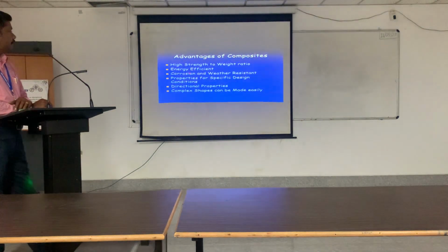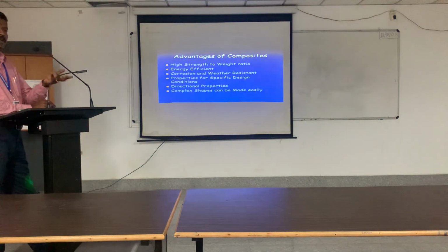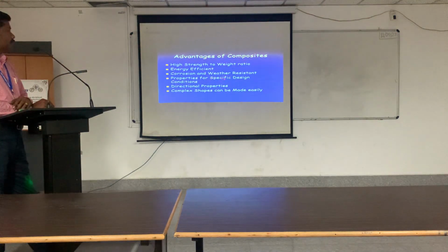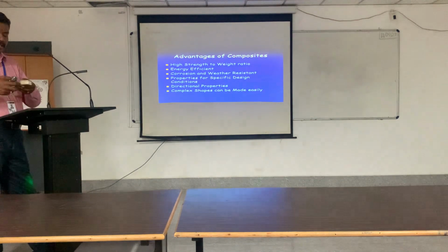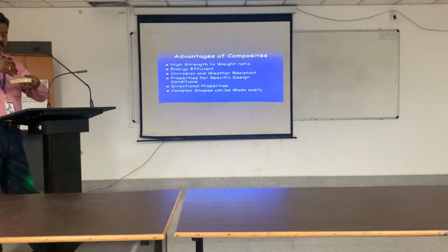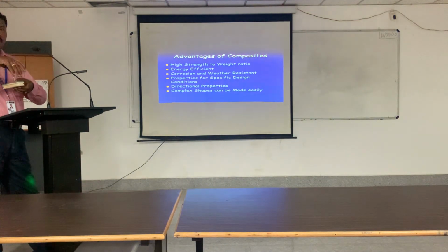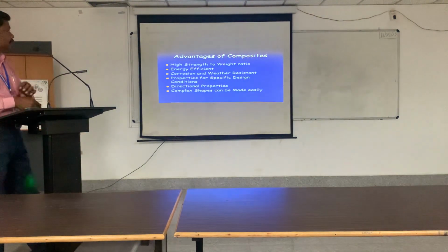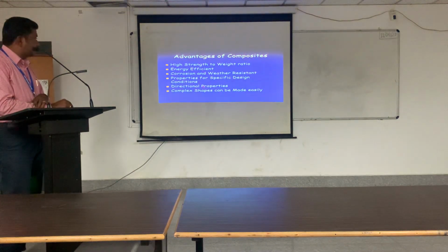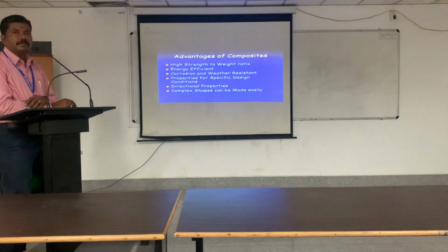Energy efficient material, corrosion, weather resistant or acid resistant, or whatever properties for specific design conditions. So whatever the design conditions may be, if the structure has to take transverse load, accordingly you can stack the fibers in the transverse direction. If it has to take the longitudinal load, you can stack the fibers in the longitudinal direction. So specific design conditions, directional properties, and complex shapes can be made very easily.